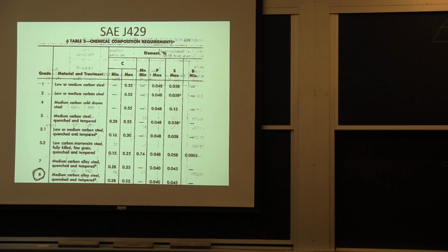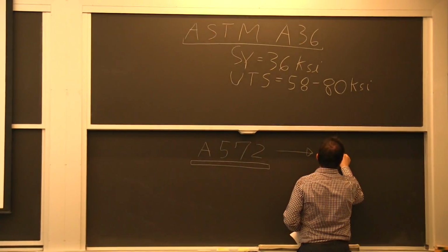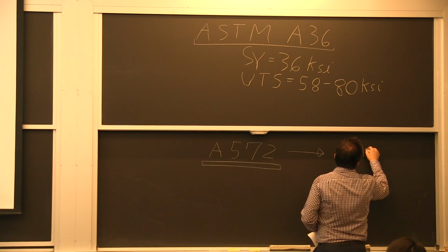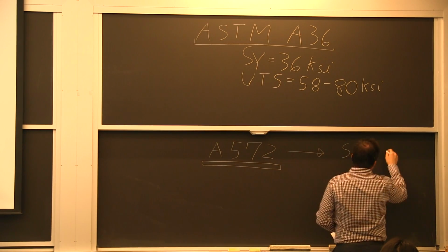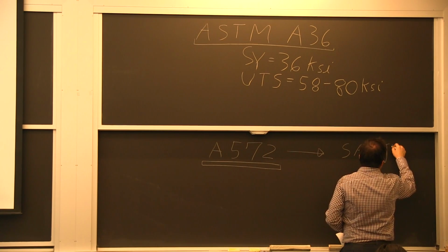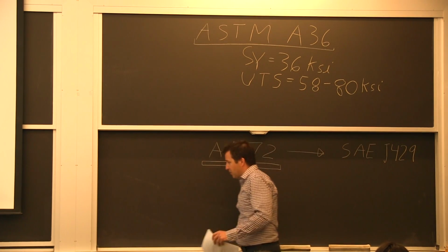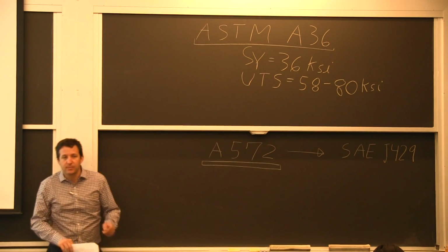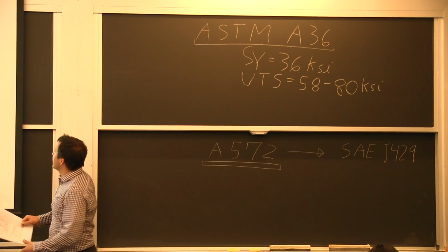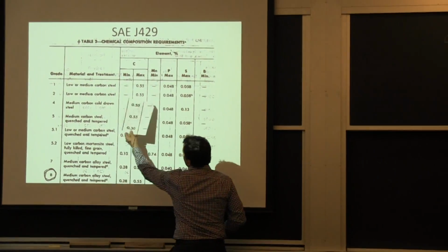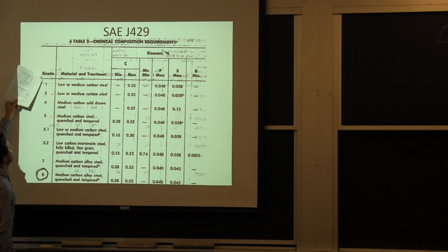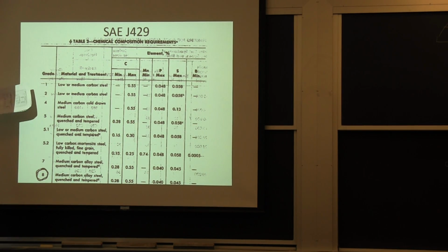These are SAE bolts. I will consider that one step up. If you ever heard of grade 5, I think if you go to McMaster, you can buy grade 5 bolts, grade 8 bolts. A lot of them come from that SAE spec. If you look here at the chemical requirements for different grades, this is very, very basic bolts. You might as well not specify what you want if that's what you specify. You just get a utility bolt.